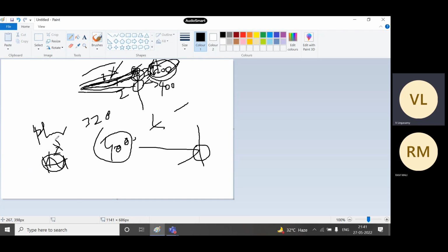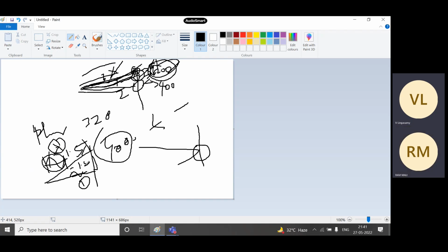Or you can see it this way: for one signal, 1 lambda takes 1 second to reach some array location. But the other path reaches its location by 1.5 lambda, so the path length is 1.5 lambda. One reaches in 1 second, the other in 1.5 seconds. So this 0.5 second is the delay, correct?